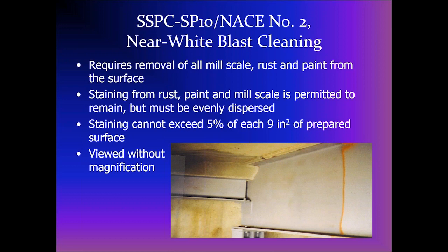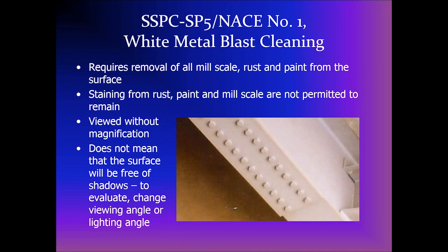Only stains can remain. The final degree of abrasive blast cleaning for steel is SP5 or NACE 1, white metal blast. In this case, everything is removed. All material, all rust, all staining, and so forth.